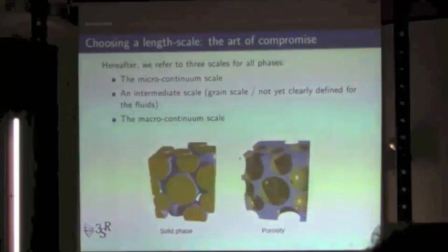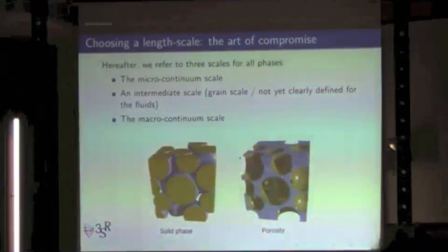Usually, or in many cases at least, this is called the vision of rigid grains with deformable contacts. I in fact don't like this naming very much, because I think it is in fact a model of deformable grains, and that's it. Simply, we don't see the details of the deformation near the contacts. They are hidden away, and they are contained in the contact law that we write. But we can associate to this free energy whatever we like. There is no difficulty. We just put all the complexity in the interaction equation.